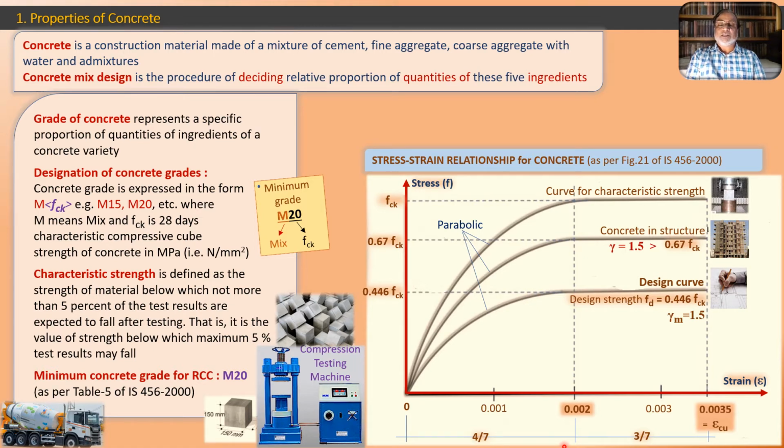They are obviously independent materials, so they have independent properties. But there seems to be a coincidence about this value 0.002. We find that the value 0.002 is the value in the stress strain curve of steel where the graph deviates from a straight line to a minor curvature and then further the plastic area. So that is the point of 0.002 value for steel.